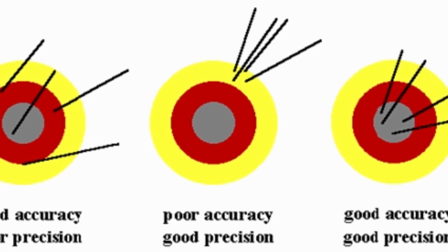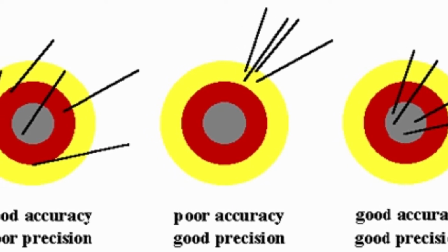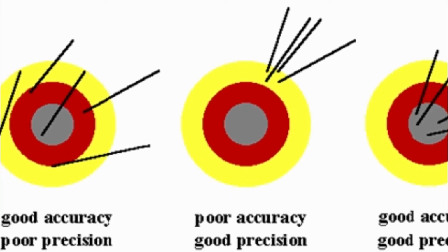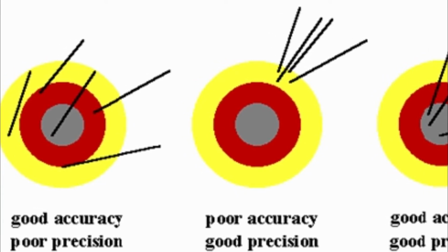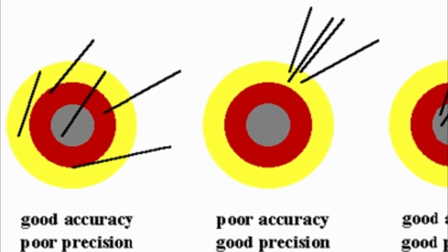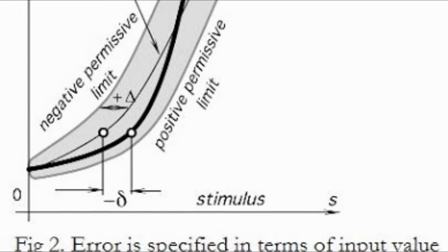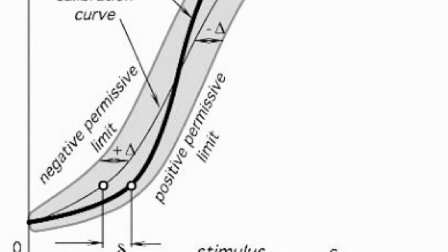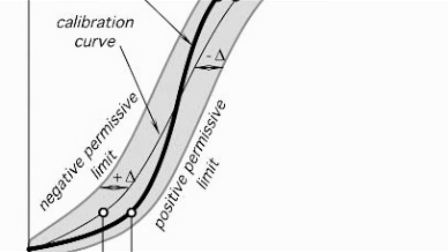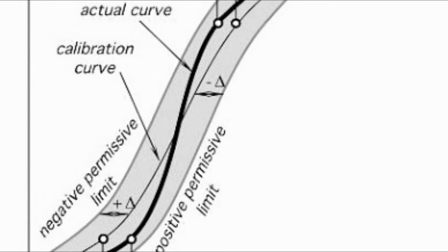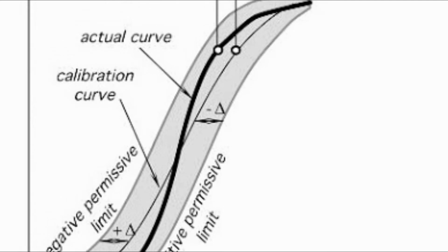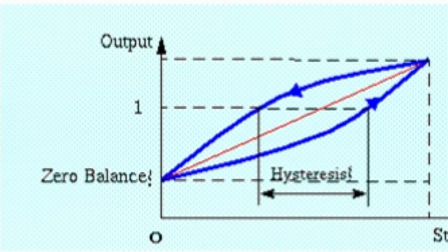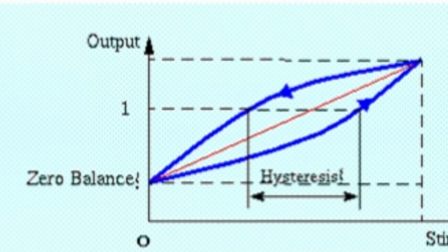Linearity. If the sensitivity of the sensor is constant for the range, then it is called as linearity of the sensor. The linear sensors are easier to use while the nonlinear sensors require complex mathematical equations to measure the physical property. Hysteresis. The hysteresis is the characteristic of a sensor by which the sensor produces a different set of outputs if the data is recorded in different directions.